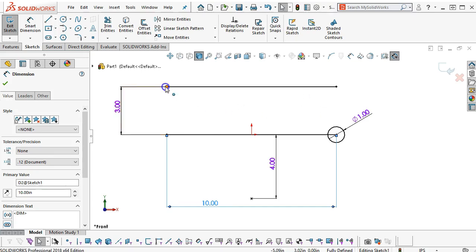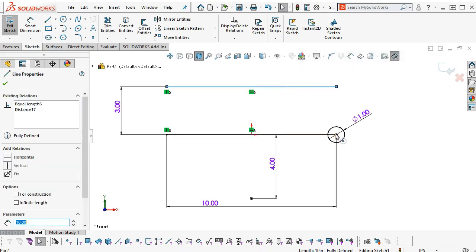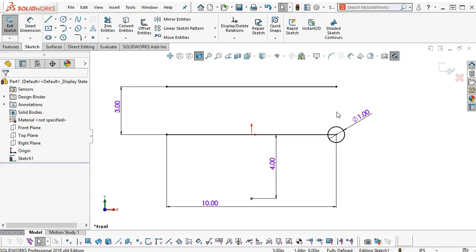And so this one was our vertical, and if I just pick on that endpoint, it's showing me only the relations applied to those two items, to those two elements. All right, so I have the object, I have its endpoint, and I want to call those elements, I'll try to stay consistent on my terminology, the endpoint element, and the line is the object between the two endpoint elements. So this one will technically be vertical as well, but it's by virtue of the equal, not by virtue that I made those endpoints vertical as well. And that would have the same net result.